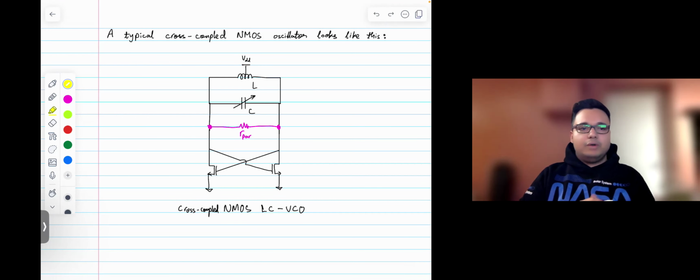There's a lot of theory about phase noise of VCOs, and power consumption, and all these different trade-offs for a VCO that we need to consider. But this is basically the working principle, and I just want to show you how negative resistance can make it possible for us designers to have an oscillator on chip.